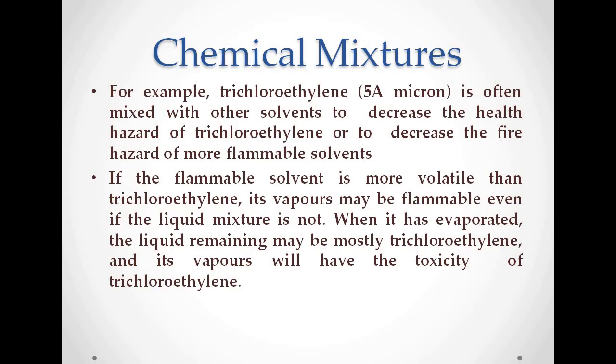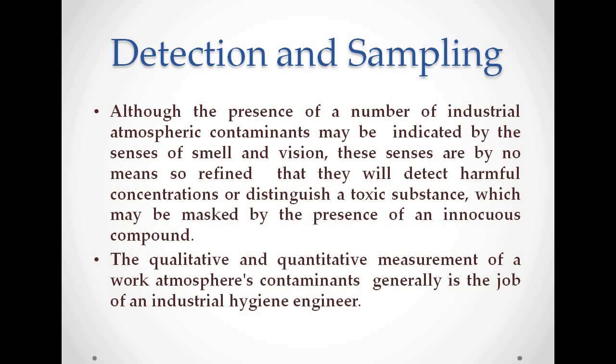For example, trichloroethylene is often mixed with other solvents to decrease the health hazard of trichloroethylene or to decrease the fire hazard of more flammable solvents. If the flammable solvent is more volatile than trichloroethylene, its vapors may be flammable even if the liquid mixture is not. When it has evaporated, the liquid remaining may be mostly trichloroethylene and its vapors will have the toxicity of trichloroethylene.